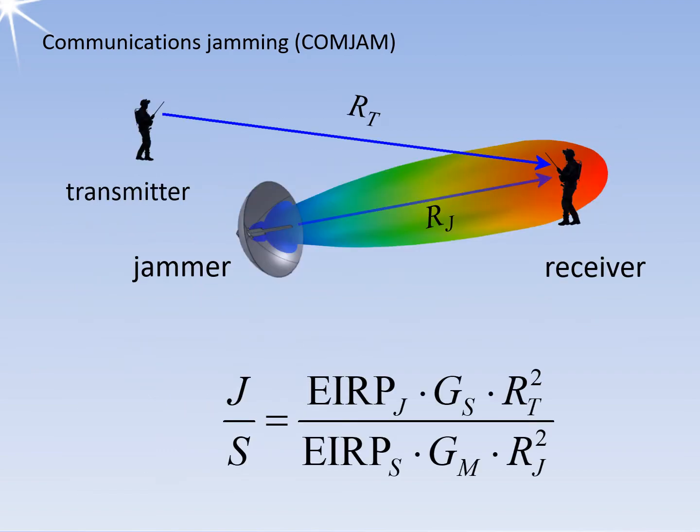Communications jamming, abbreviated to COMJAM, refers to the deliberate interference of communication signals. Typically, this involves tactical HF, VHF, and UHF signals using noise-modulated cover jamming. However, it can also include jamming point-to-point microwave communications links or command and data links to and from remote assets. Note that you can only jam the receiver. The enemy's communications link carries a signal from a transmitter to a receiver.